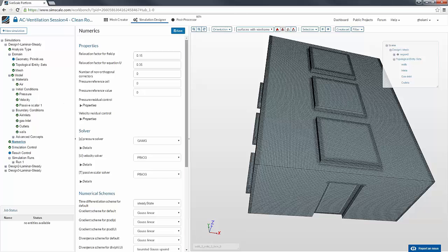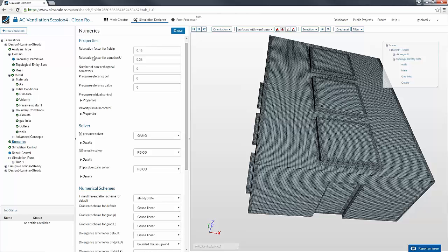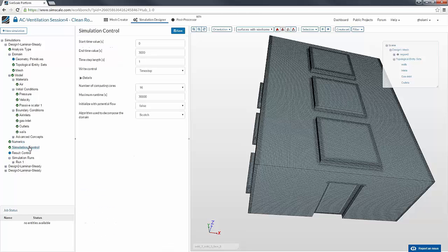The numerics also, we changed them slightly to use a little bit of relaxation for pressure and velocity, and we also used the multi-grid solver for pressure. Since this is a little outside the scope of what we're discussing here, I will not go through more details, but of course, I'm open to discuss this in the community if anybody in the forum is interested.